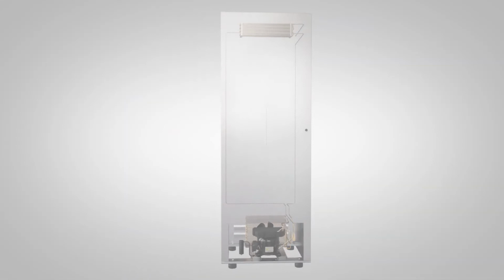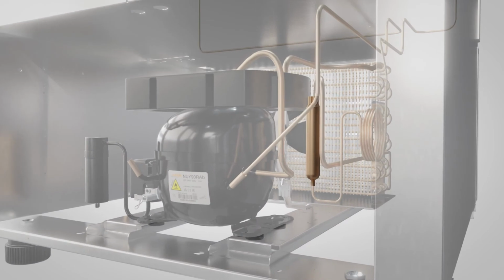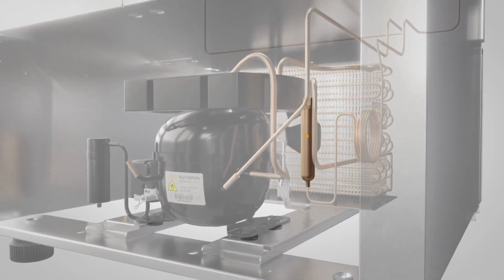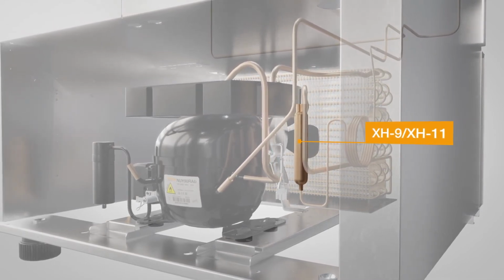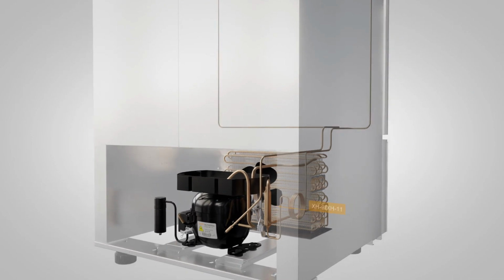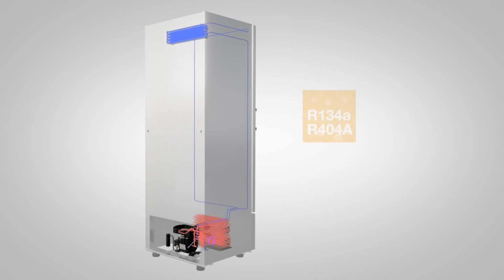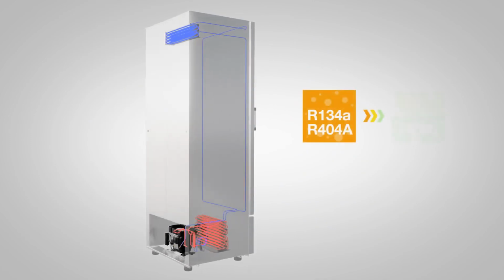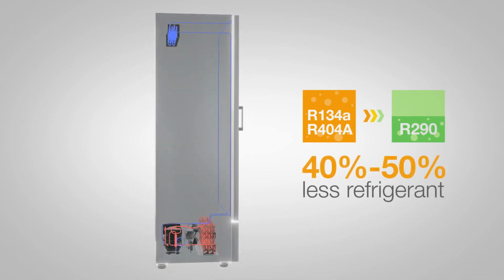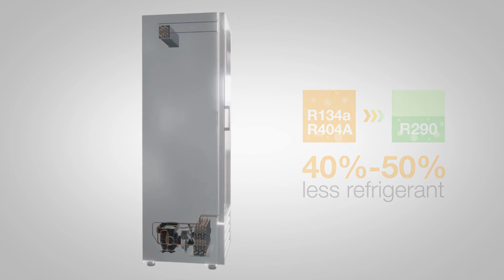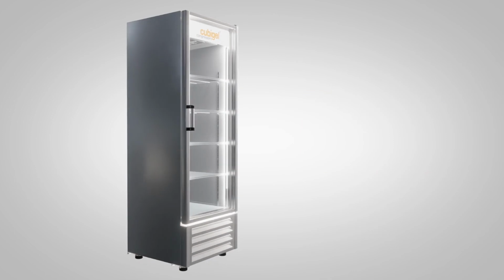When changing an HFC system to a propane one, it is recommended to change the filter dryer. For propane, it is recommended that a XH9 or XH11 filter is used. The amount of refrigerant always depends on the type of system and its components. Changing the system to the R290 means approximately 40 to 50% less refrigerant charge compared to the R404A. Furthermore, as it is a pure fluid, the refrigerant can be charged in liquid state or gaseous state.